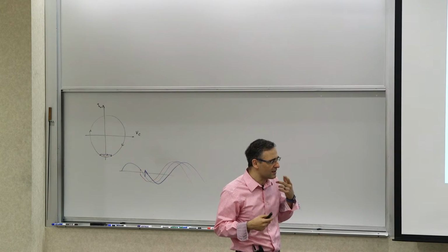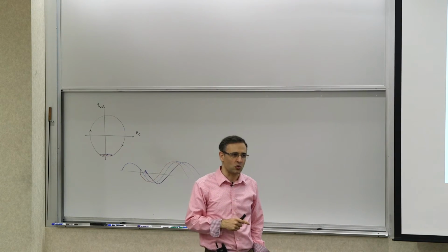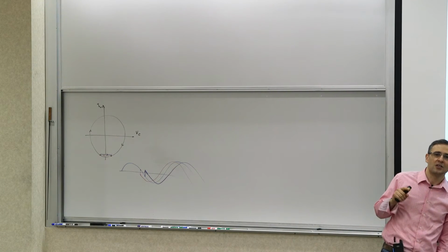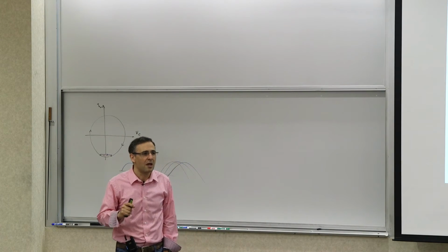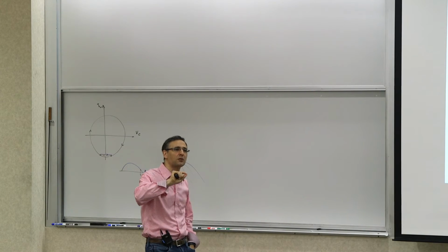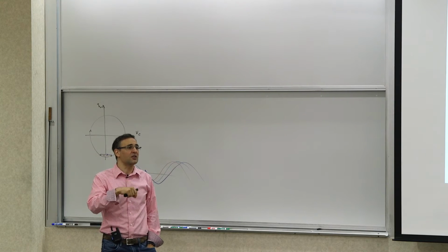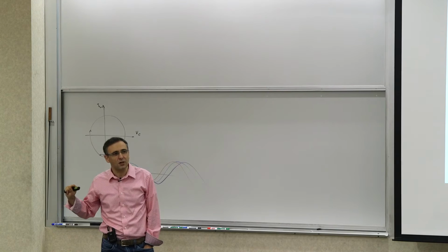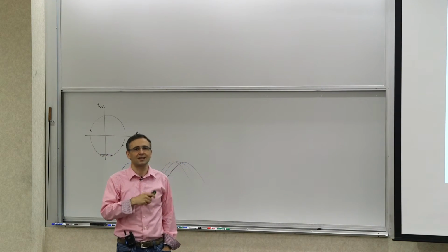So let's start with the first concept, which is what we call cyclostationary noise sources. That sounds like a mouthful. What do we mean by cyclostationary noise sources? They correspond to noise sources whose statistical properties change with time. In general that is a non-stationary noise source, but cyclostationary means that the statistical properties change in a periodic fashion. Now, what does that mean? Let's look at an example.